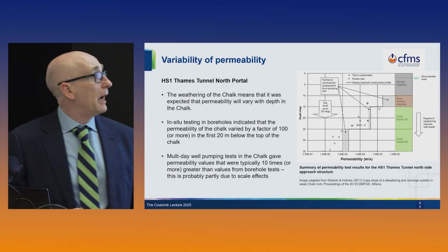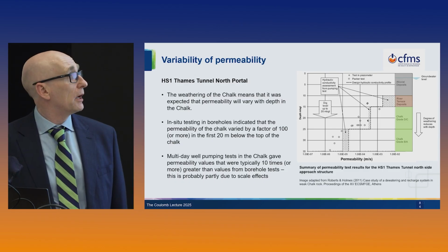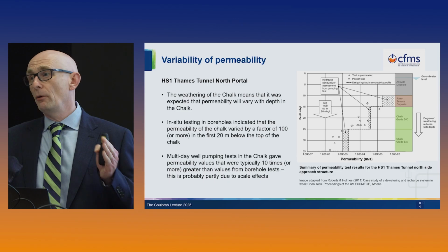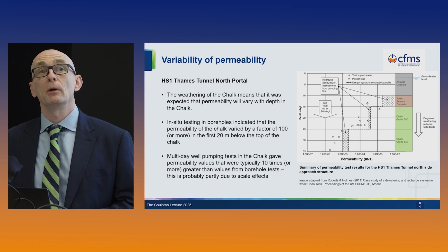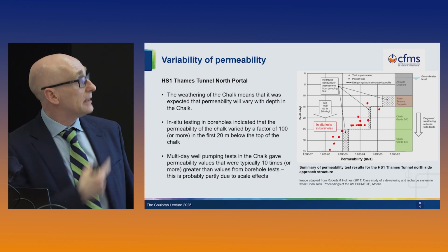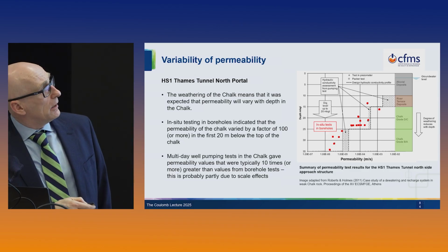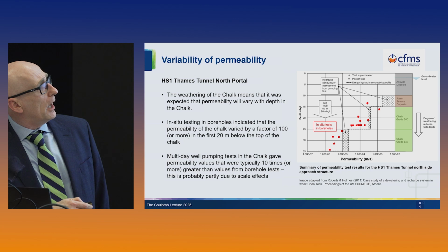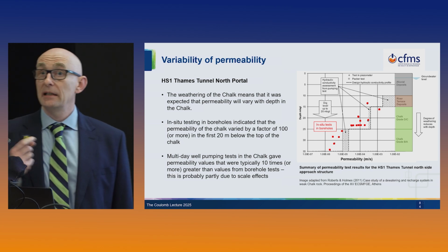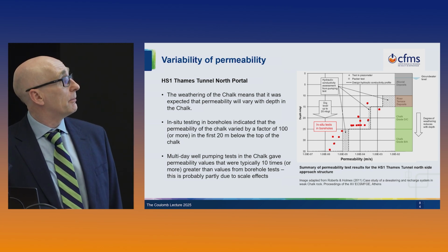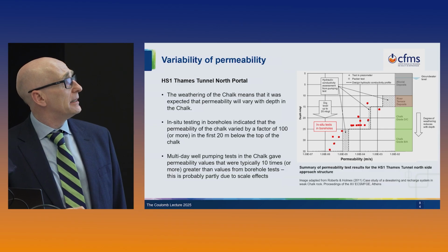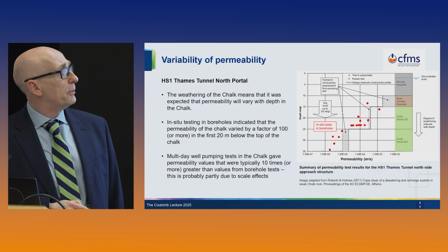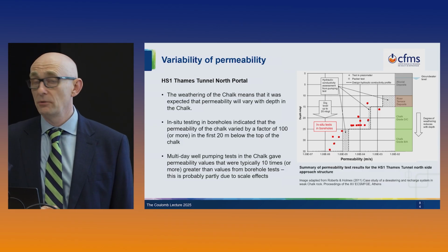So we carried out quite an extensive investigation programme, and we carried out quite a lot of borehole tests. These are the small-scale tests, both falling head tests and packer permeability tests, Lugeon tests, and these are the data from that. So we've got the chalk here, so the top of the chalk is about 15 metres below ground level, and each of these red dots is a data point from a test in a borehole at a particular depth. And you can see that over the 20-metre depth below the top of the chalk, there's a reduction in the permeability of the test results.